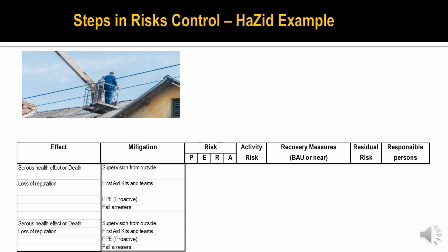What is a fall arrestor? It's going to minimize the height he is going to fall. A fall arrestor can be anchored either onto the roof of the building or to the man basket. It is always better to anchor it to a permanent place, that is the roof. So before he starts walking around the roof, he has to anchor himself after wearing a harness.